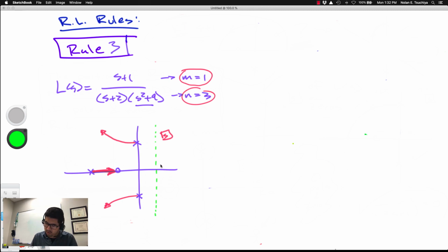So that portion of the real axis should not be on the root locus. That's good. In here, between the poles on the imaginary axis and the 0 at -1, I am to the left of, well, this should be an x. I am to the left of 2 poles and zeros. So this point here on the real axis should also not be part of the root locus.